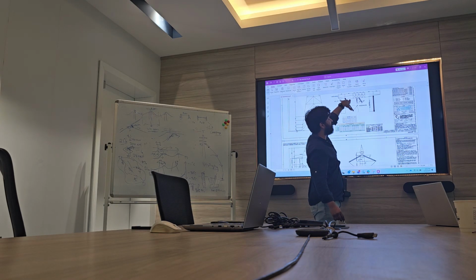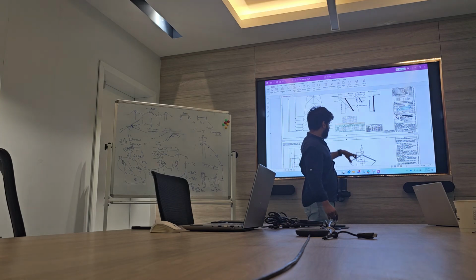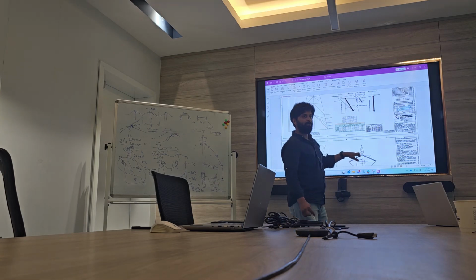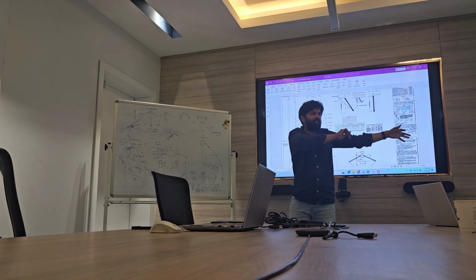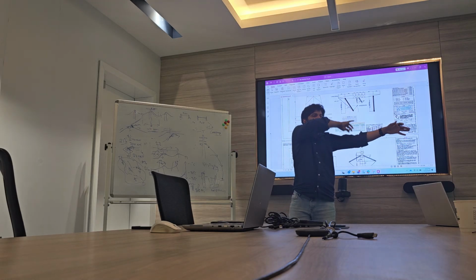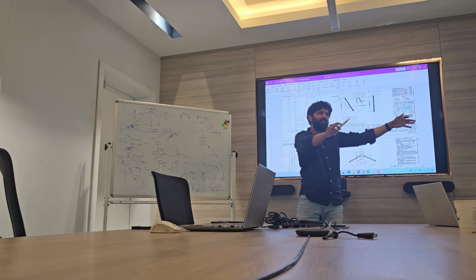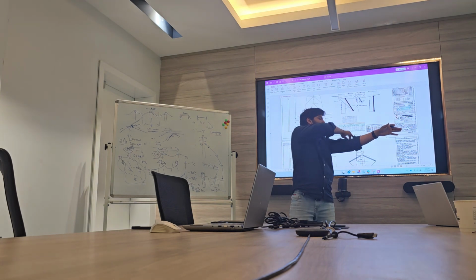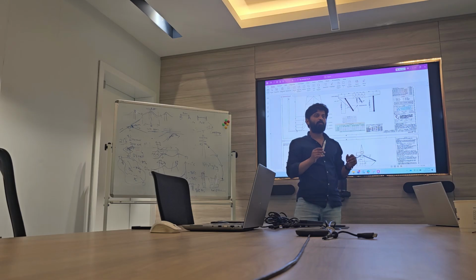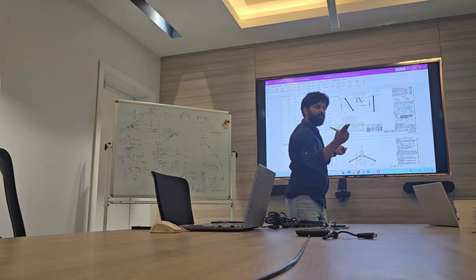If you see, this is a plan view from top. This is the side view. The tower is here, transverse face, I have a tension insulator here and one on the back side, and then I will bring the conductor, cut it at the insulator, take the conductor, cut it at the insulator. Now my insulator is cut from both sides.